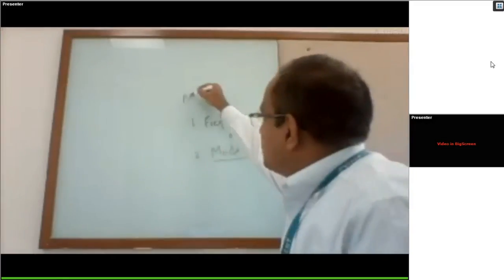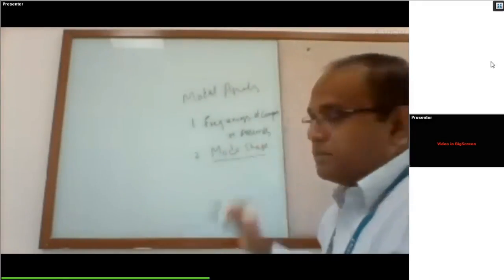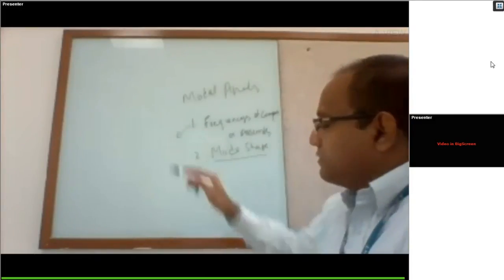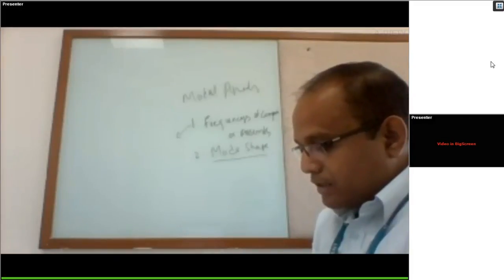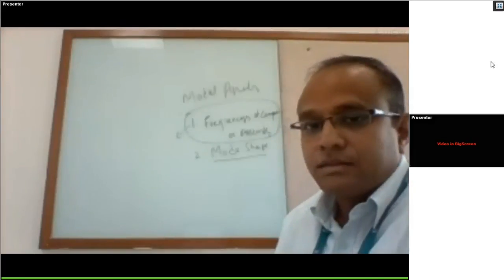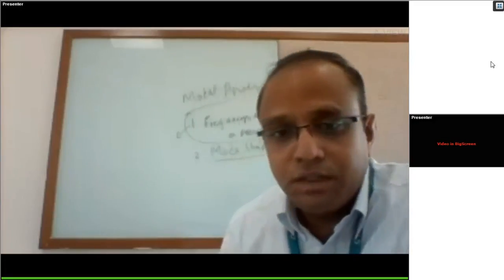Modal analysis is performed to extract frequency and mode shape. Okay. So the great question comes: why do we need to extract frequency? The main reason is we need to check the resonance with the operating frequency. So one of the important things is, what will happen if it matches?